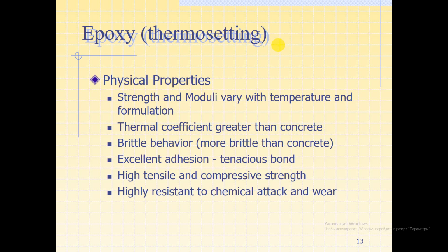Epoxies are used as powder coating for a variety of applications. Fusion-bonded epoxy powder coatings are extensively used for corrosion protection of steel pipes and fittings used in the oil and gas industry, potable water transmission pipelines, concrete reinforcing rebar, etc.